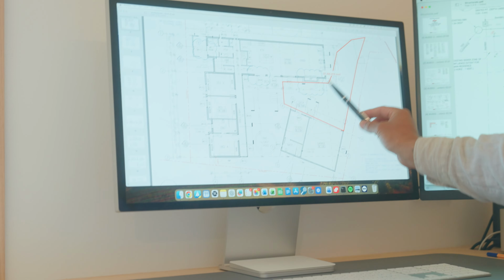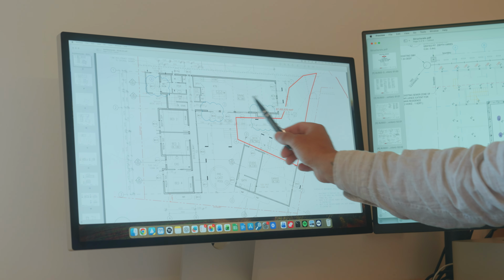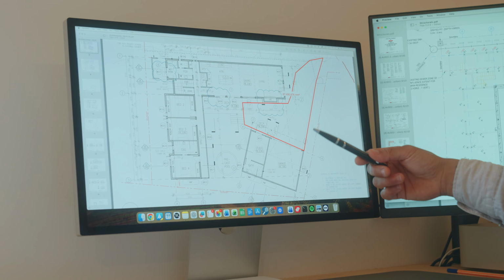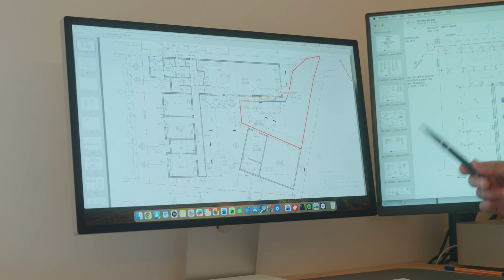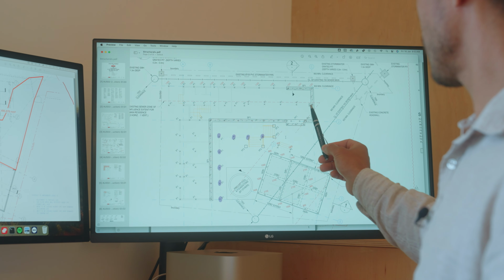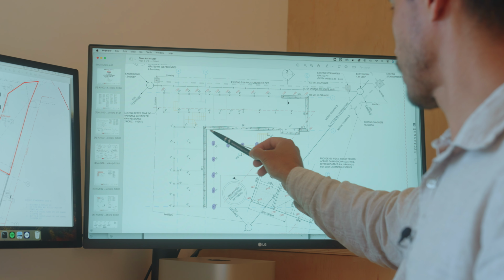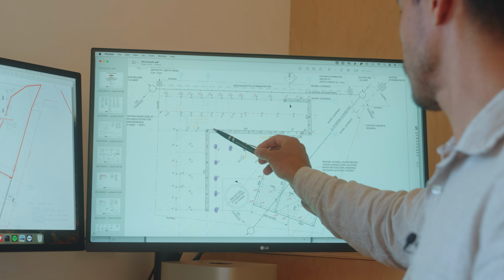Another really important set of documents is the engineering. For instance, again, this is the floor layout of the house. We don't actually know how it's going to be built. We can make assumptions from stage one, but we don't know how it's going to be built until the engineer gets involved. For instance, you can see here, P1 is actually screw piles, and along here is a type of strip footing and then brickwork on top of that.